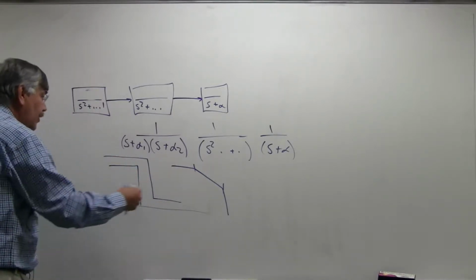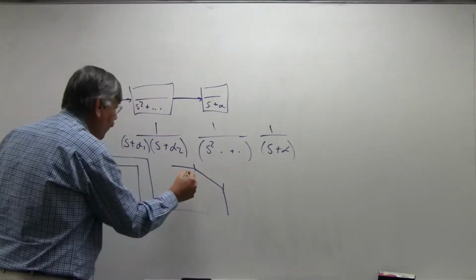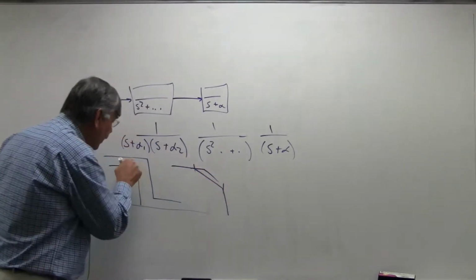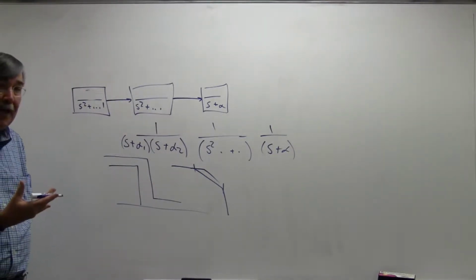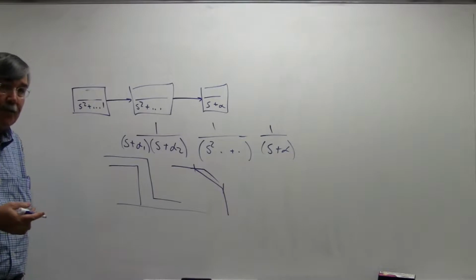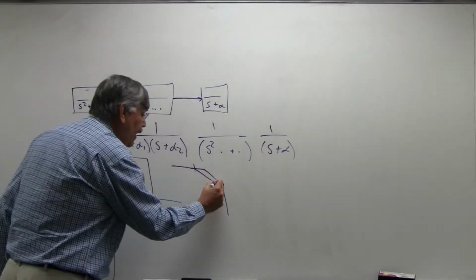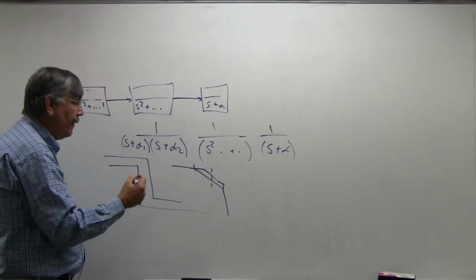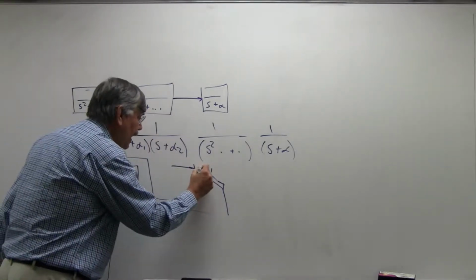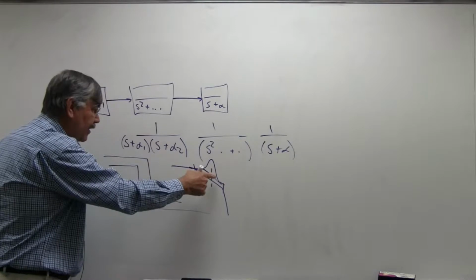So to increase the selectivity, we want to move these poles closer together where they can tuck into this corner more. And if you remember, moving the two poles together is exactly what we meant by increasing the Q. And then if we move them so that the poles would almost appear to meet, then as we increase the Q more, we're going to get some peaking.